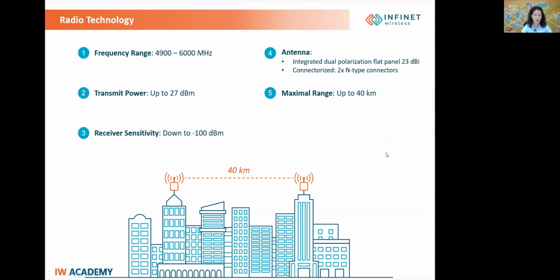There are multiple options for choosing the channel width. This is particularly useful in case of interference that overlaps only with a small part of the channel. In classical systems, you will have to reduce the bandwidth to half, so the capacity as well is reduced to half in order to be able to remove the effect of the interference. With Quanta 5, you can adjust the bandwidth gradually in order to adjust to the specific scenario and achieve a minimum capacity reduction.